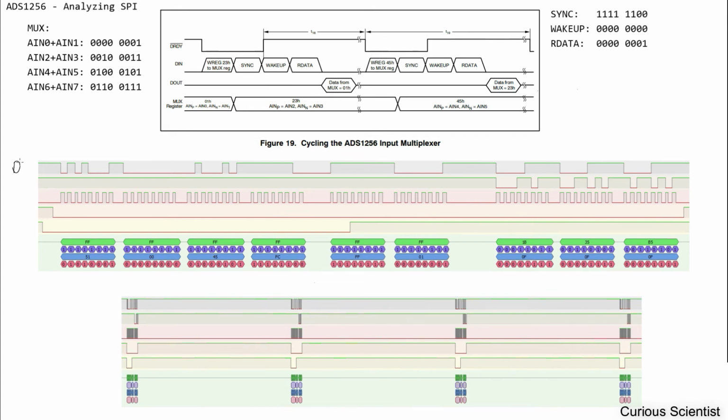So here again, just to see what is what, I write here the names of the channels or the signal lines, and then I already put in a few things like the multiplexer values if you want to combine two channels together, and here I'm using the channels in a differential mode, and also I put here the most important data in bits, so you can see them because we will use the things here.